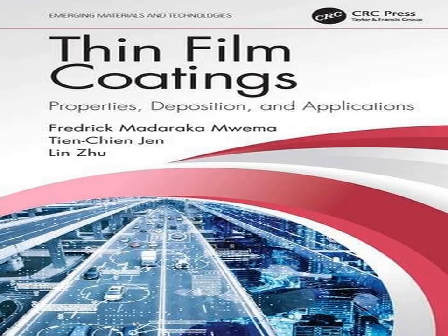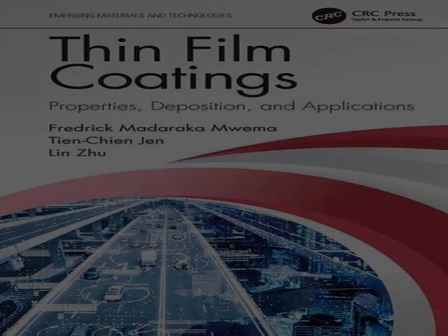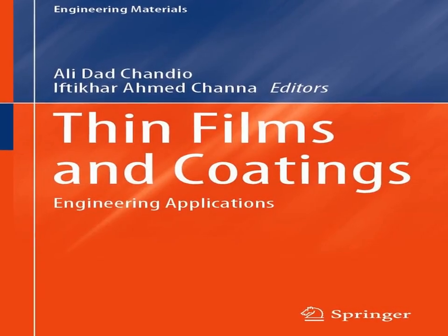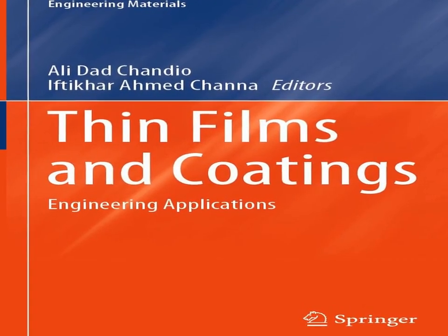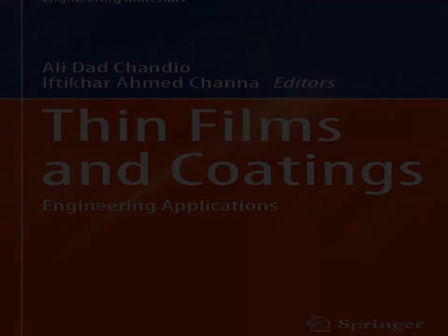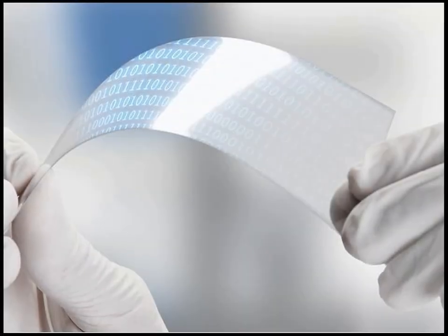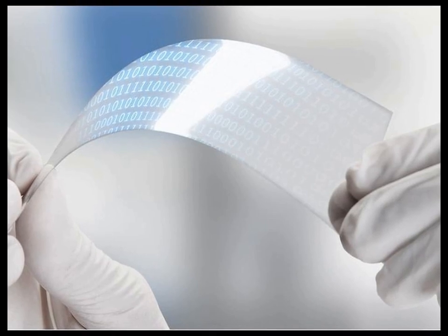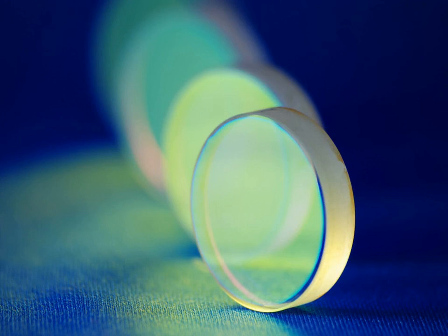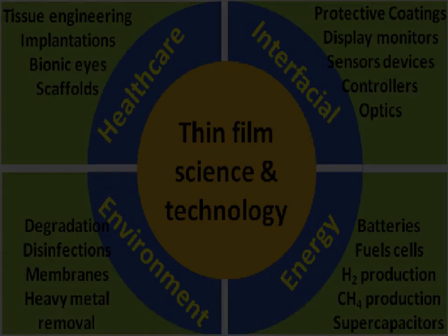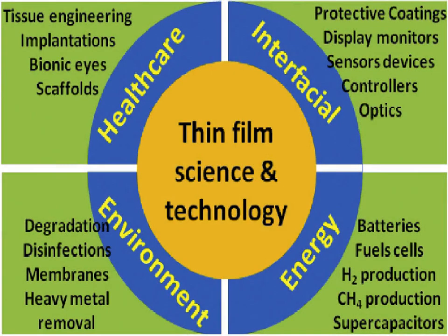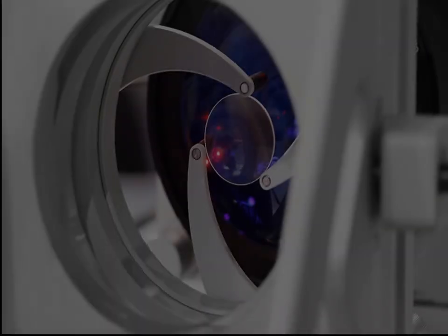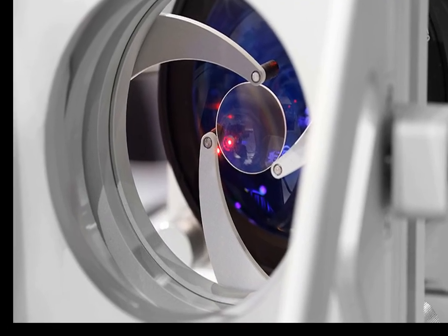Electronics heavily rely on thin films for semiconductors, dielectrics, and interconnects. Gate oxides have evolved from SiO2 to high-K materials like HfO2 to reduce leakage in nanoscale devices. Conductive interconnects use copper with barrier layers like TiN or TaN. Thin film transistors made of amorphous silicon, IGZO, and GaN power large-area electronics. Magnetic films such as permalloy or CoFeB enable memory devices and hard drives, while superconducting films like NbN and YBCO are vital for quantum circuits and photon detectors.